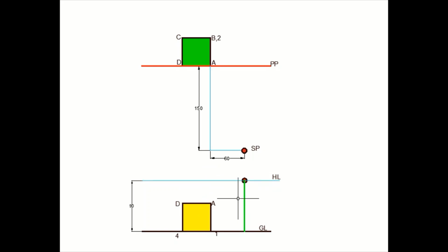Now beyond this there is some procedure that needs to be followed. Another important point to be noted, unlike the orthographic projections, in this case the top view is placed on top and the front view is placed below the top view. The entire discussion we had so far is all about the concept, how to reach these two views, the top view and the front view. Now beyond this there is a procedure to get the 1-point perspective view of the given object.